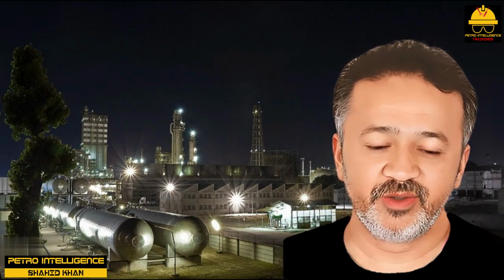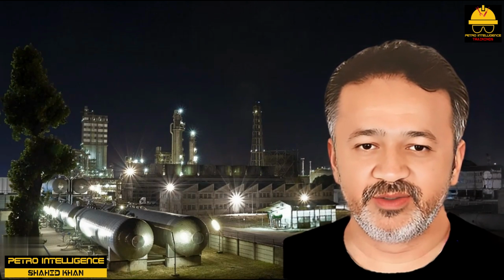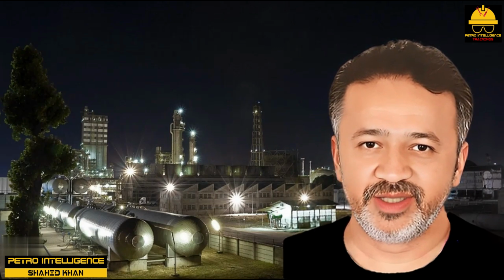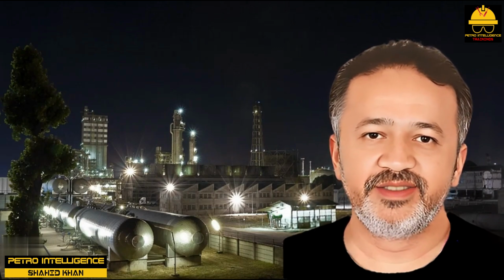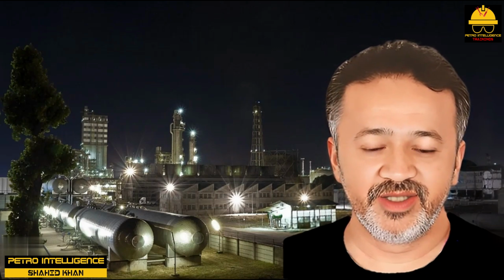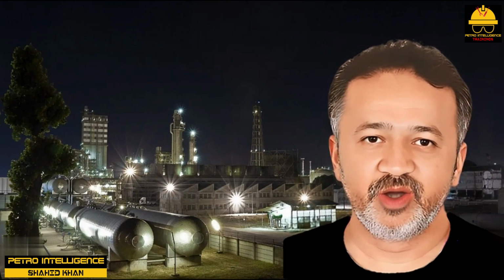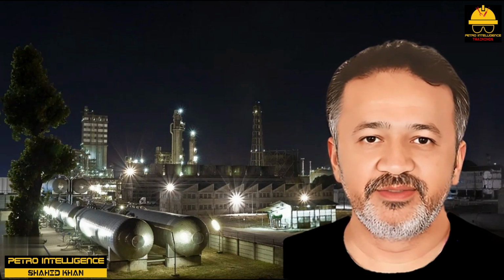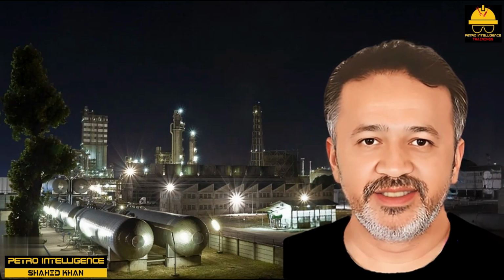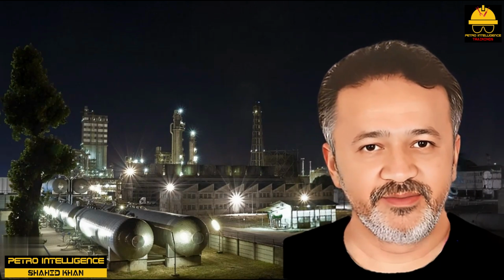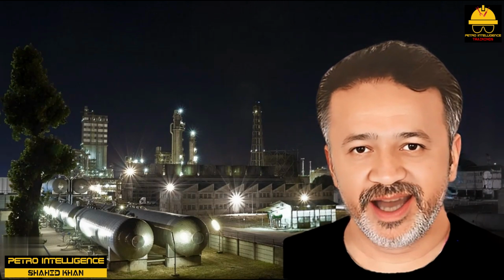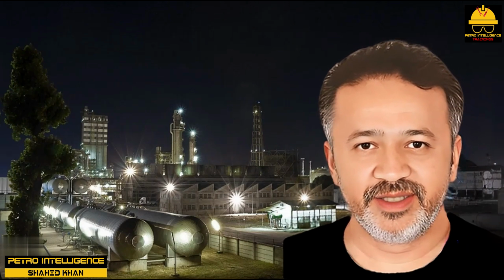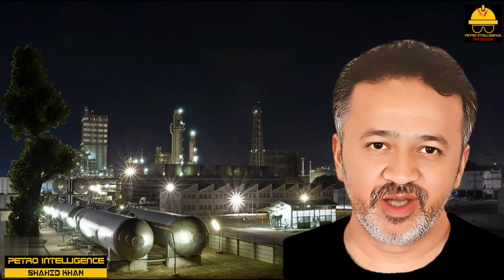What is wanted is a way to accelerate the conversion of the sulfur molecules attached to the diesel to H2S at a moderate temperature, about 700 degrees Fahrenheit. That's what a catalyst does. It does not change the equilibrium, it just makes the reaction go faster without having to increase the temperature. For a catalyst to be effective in accelerating the rate of reaction, it has to come into contact with the molecules of the stuff that's reacting. That's why catalysts have lots of surface area. Most of the surface area of a pellet of catalyst can only be seen with a microscope.